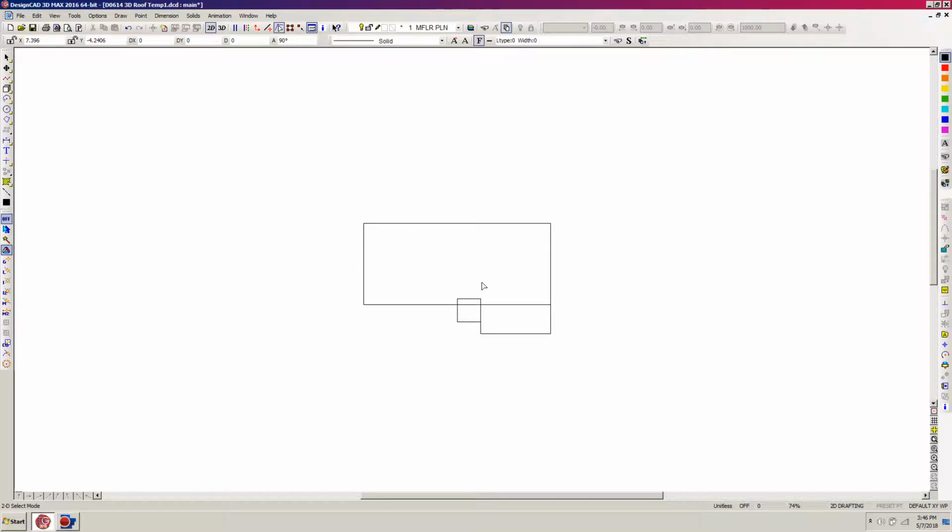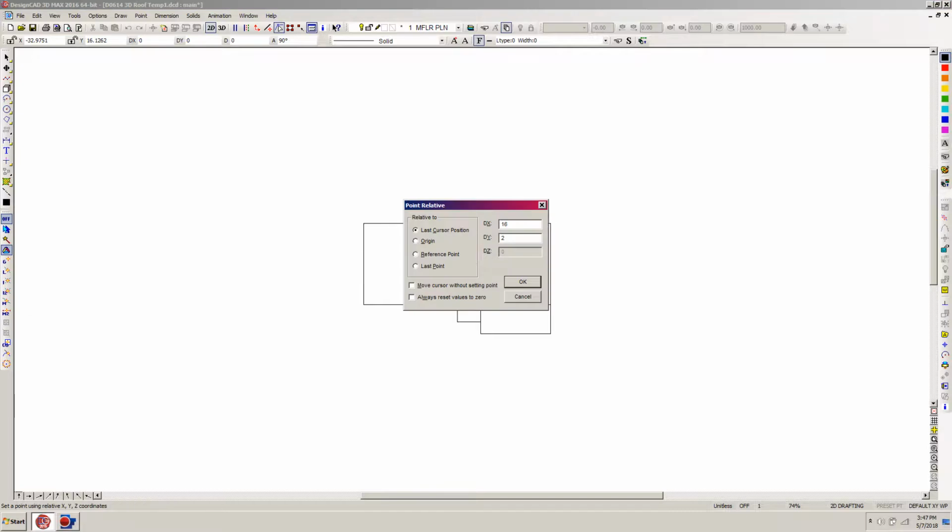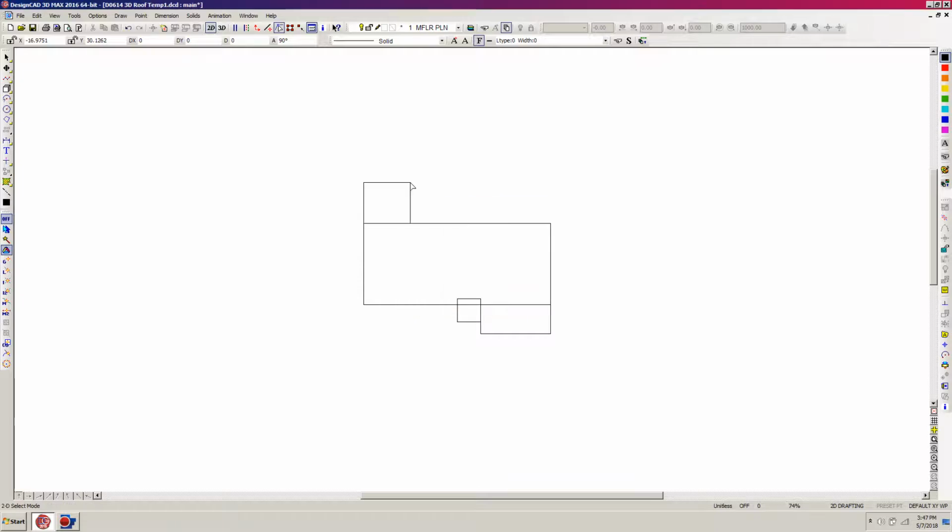And I'm going to also have a master bedroom off the back. And I think I'm going to make that fairly nice when I'm going to have it project out. Let's take it at least 16 feet wide, and I'm going to take it out about 14 feet. So I'm going to hit the 2D box command again and just right click. And I'm going to go 16 on the X, and I think 14 on the Y will give them a decent size. Okay, so that is basically the outline of the house.